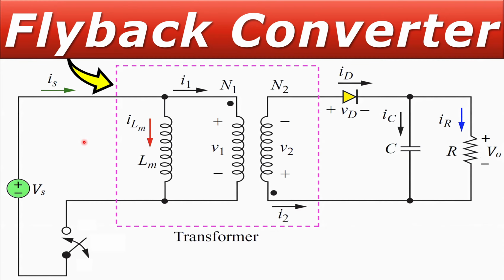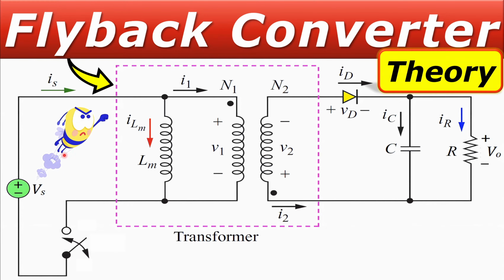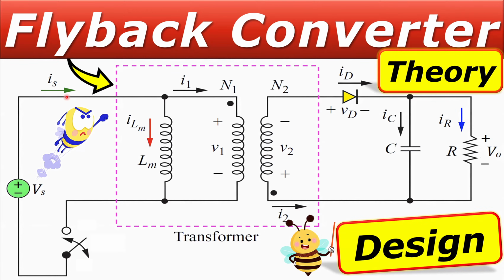In this example, we will discuss the flyback converter. First, we'll start with the theory and develop the required equations for our design. In the next section, we will then discuss how we can design a flyback converter from the specifications. Of course, we will see everything step by step in our calculations and verify these in MATLAB Simulink simulations.